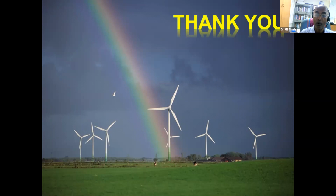That's why, once you are going for more renewables, another issue is your frequency response. They have less inertia. So if your thermal power stations are off and you are using only solar and wind, the inertia of the system is low. So a sudden change in demand and supply will cause fluctuation. So we require virtual inertia.